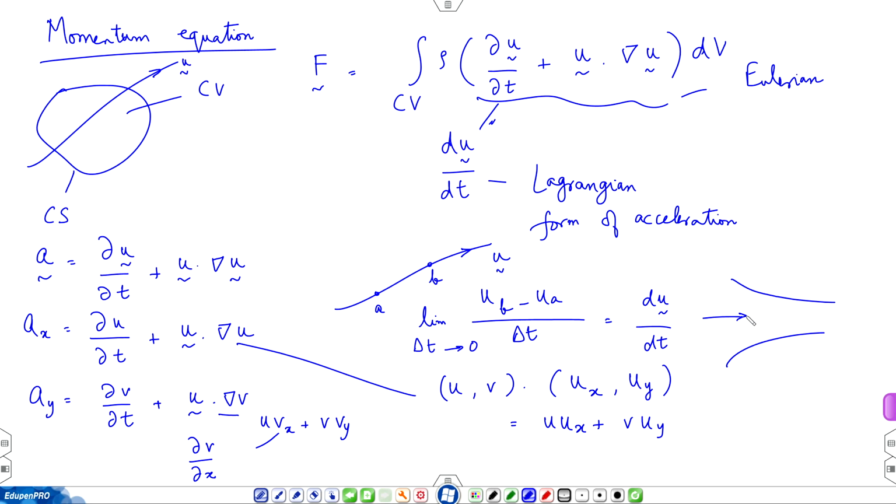So, that is an example of spatial acceleration. So, u x in the nozzle problem will not be 0, it is greater than 0. Similarly, in a diffuser, velocity is decreasing in the flow direction. So, u x will be negative. So, this is spatial acceleration, even though the temporal terms may or may not be 0.